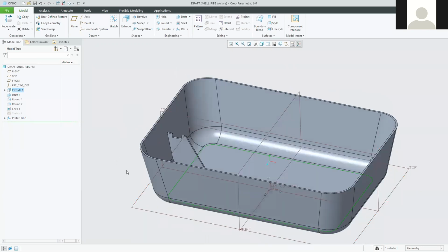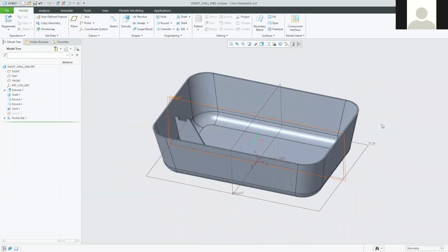So those are the two ways that we've created sketches up to now. But what we can also do is create our own planes. In the same way that the top plane is there, we can define our own plane that we can have in any position that we want. So that's what we're going to do for this feature. How are we going to do that? One of the ways is to create a plane which is a set distance away from one of the datum planes, or from one of the base planes. So that's what we're going to do in this example.